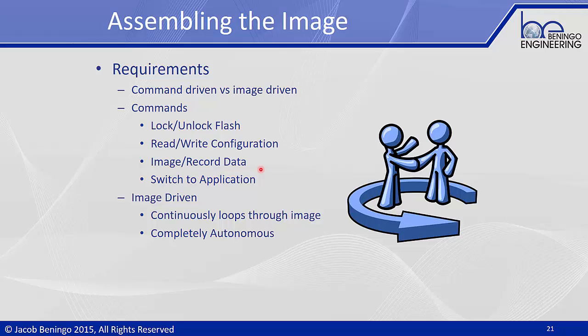So we're going to take the application image from our PC and transfer it bit by bit down into the microcontroller. And then, of course, a command to say, if you're in the application, reset it in the bootloader. If you're in the bootloader, reset it in the application code. So there are some commands we're going to want to consider there. As I mentioned, this is far more complicated to implement than simply having a thumb drive you plug in, where the embedded system goes out, reads the file on it, and updates itself. So image-driven is pretty self-contained, very autonomous, whereas command-driven, not so much. A lot of extra tools we have to develop in order to get that process to work properly.